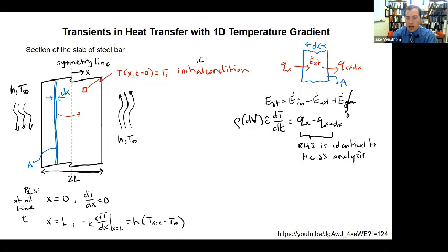So if we go and apply all of our steps, we apply the Taylor series expansion, we substitute in Fourier's law, we're going to come to the same place. Everybody agree with me on that? We're just doing a little quick differential analysis, and I'm screaming through that part because we've seen it before. So we're going to end up with a minus d/dx. We will have substituted in Fourier's law, and we would have had a dx. So this outer derivative comes from the application of the Taylor series expansion, and this inner stuff comes from the Fourier's law inside the parentheses.